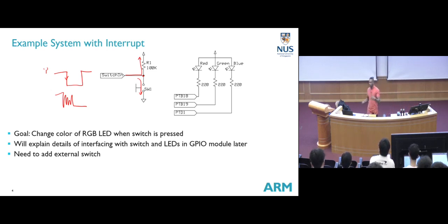If you recall what we did in EBP2, one of the solutions we implemented is a timer interrupt delay, where the moment I first get the interrupt, I start a timer and wait for some time before I continue, so I do not keep entertaining all these false triggers because of the bounce.